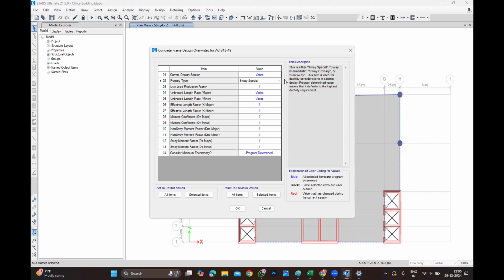You need to make the entire slab a transfer slab. You made those slabs 1.2 meters thick. On the 4th floor, imagine, it's an elevated raft. The 4th floor slab is 1.2 meters thick in order to take all the new planted columns from both floors. Understand what I'm trying to say? Because all the columns are going to stop.